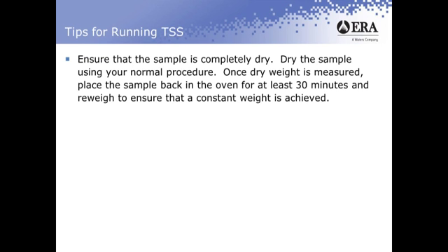You're going to measure that on your balance. What I'd recommend doing is once your dry weight is measured, take that sample, place it back in the oven for at least 30 minutes, cool it again, and then reweigh to ensure that you've got a constant weight. That's the best way to ensure that you've driven off all the moisture from your sample. If you don't drive off all the moisture, then you're going to end up getting high results.